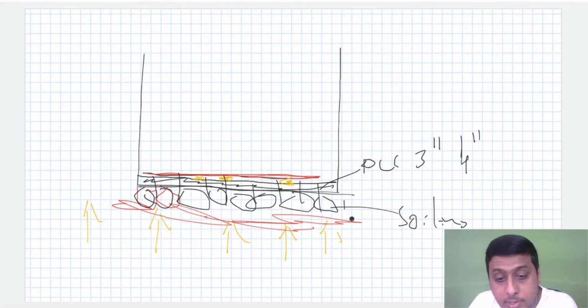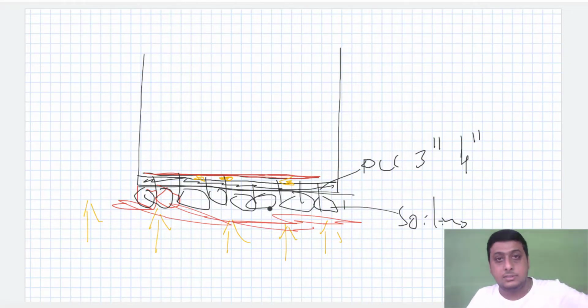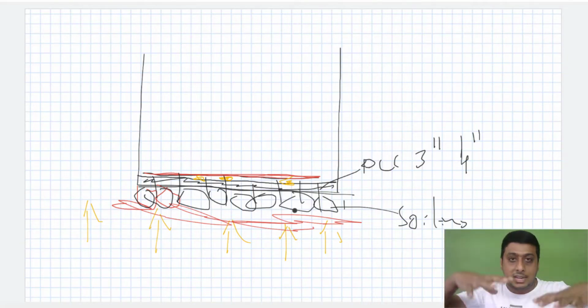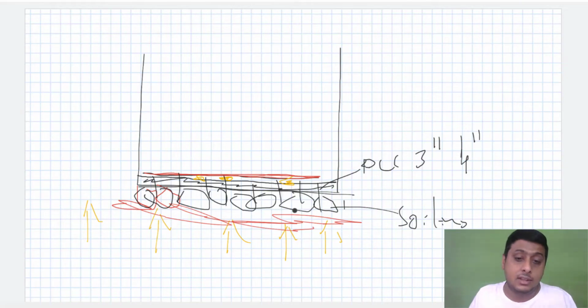Another reason is that because of loose earth, there may be deflection, meaning settlement in the foundation level. If we fill in these boulders, it gives a certain grip for the foundation, so that the settlement will not be as expected; it will be within the limits. These things will be specified by the structural engineers.